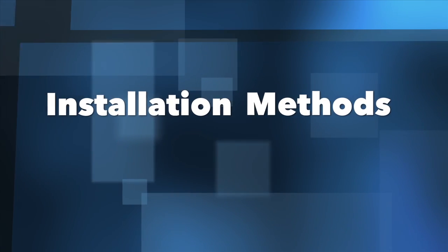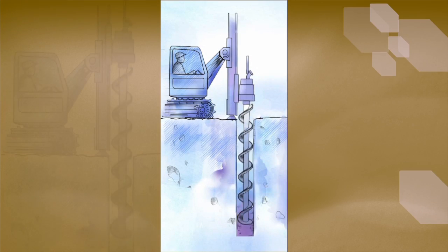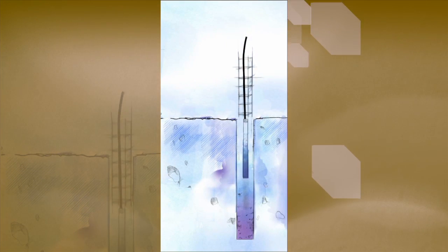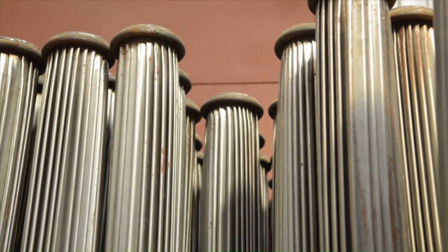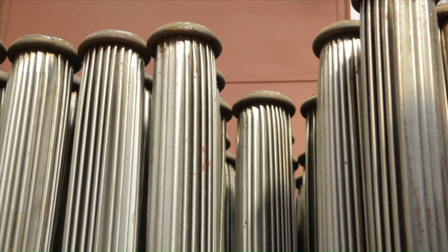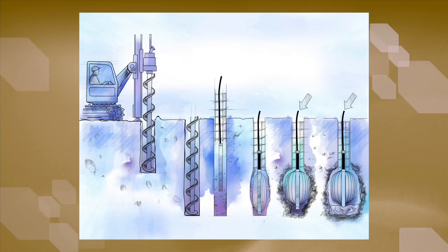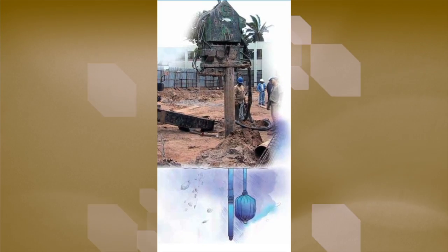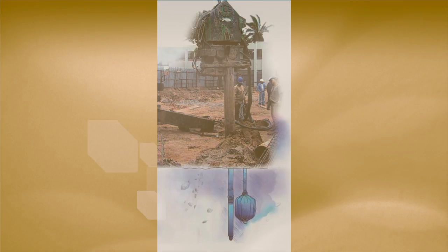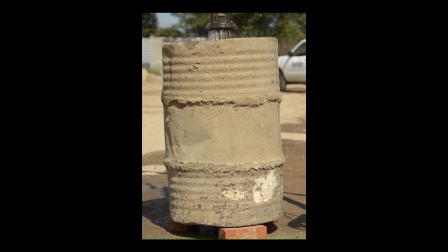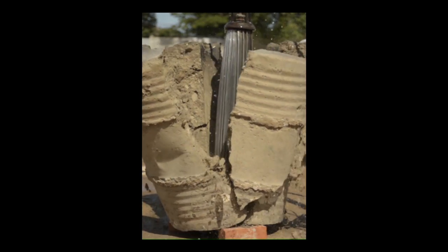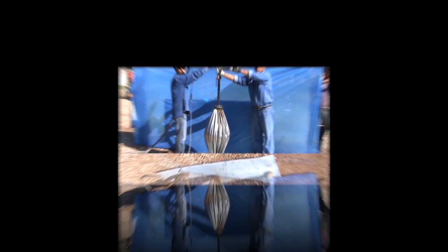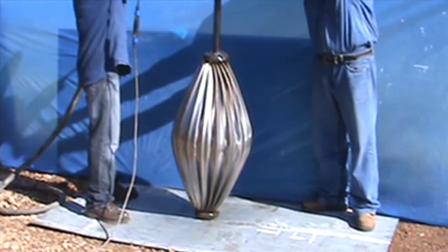Installation methods. The EB pile is very effective when installed in loose to medium-dense sandy and silty soils. As the EB cross-section before expansion is small, installation of EB piles can be by conventional drilling, driving, jacking, vibration methods, or by placement in a pre-formed hole. The grouting process of the liquid EB takes place under controlled conditions without leakage. Thus, it is possible to measure the gradual increase in EB volume and the required grout pressure.